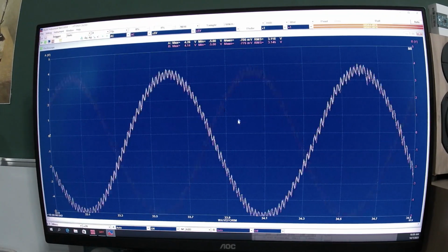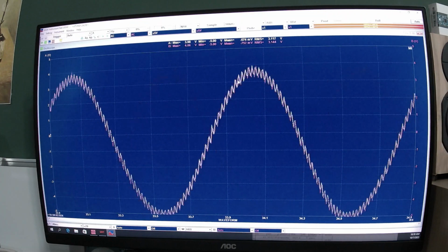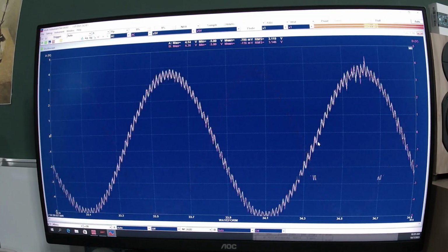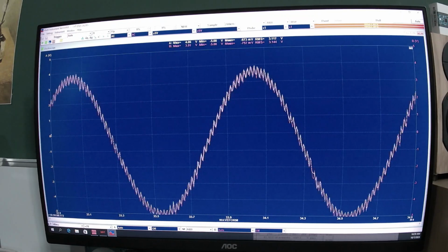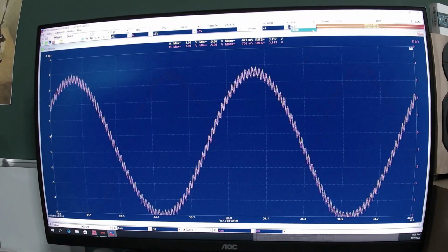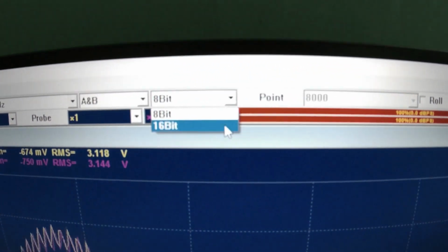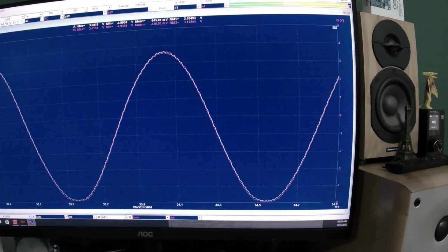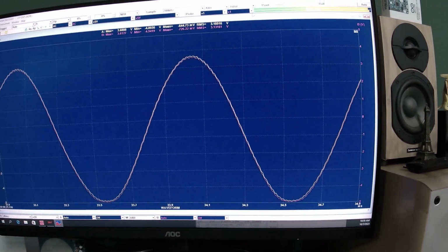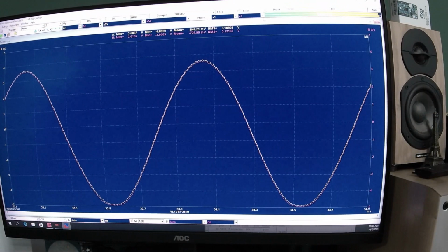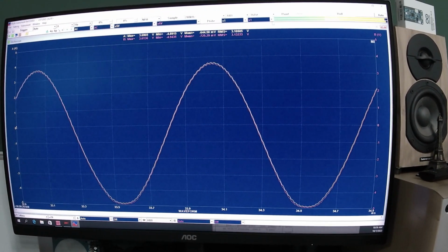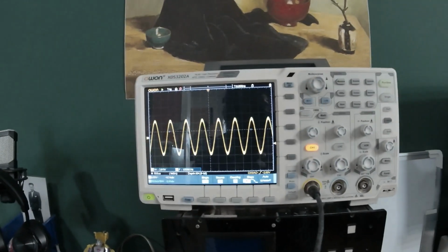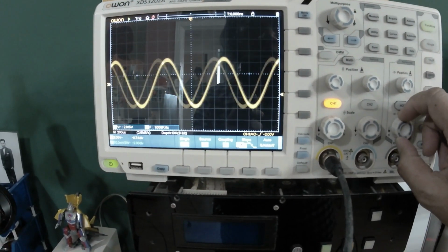So the DAQ or DAC sampling is much lesser, so you can see the real stuff in here. That's pretty scary, right? And when I change that into 16-bit, you can see what happens. It's finer and nicer, and that explains a little bit of the measurement limitation, which is why I'm using the standard oscilloscope, just not to be fooled by it.